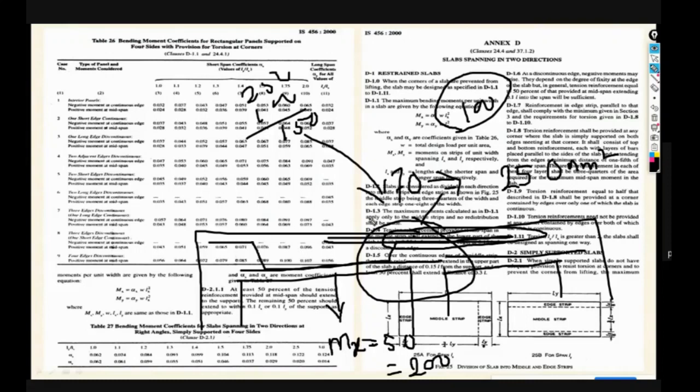So which method is much more economical? I am asking with respect to the optimization of reinforcements. Basically, if you compare these two, the bent up bar is generally required to resist the shear forces. Here we are not providing stirrups in the slab, correct?